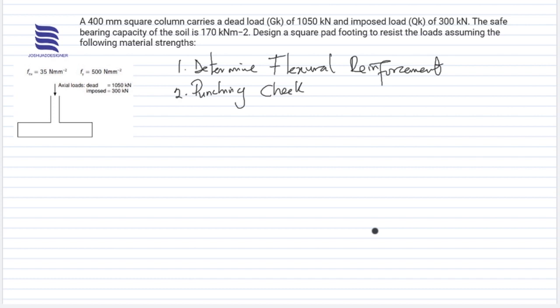Right, so but before we would go ahead, I would like to make a note following our previous designs on pad foundation. Right, so while we were obtaining the area of base, we applied the formula, the load, that's the serviceability load, divided by the soil or safe bearing capacity.